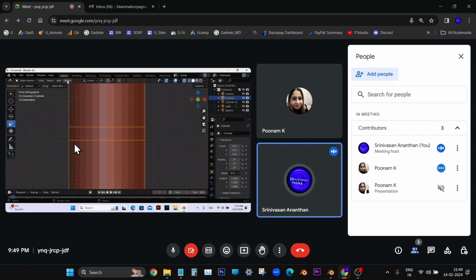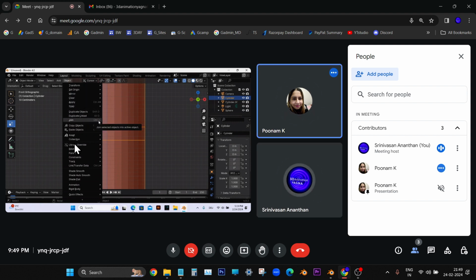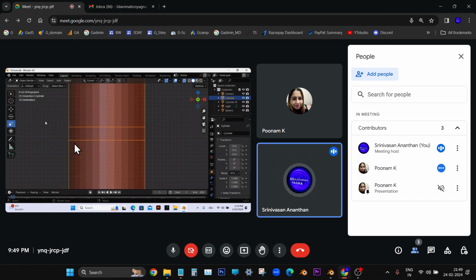Do you see the join tool is there? This is the one we used actually. Now we don't have to use it again. So Control J is a shortcut for that. In case you forget Control J, but you know the concept that we have to join, at that time you can go to the object menu and press the join tool, right.